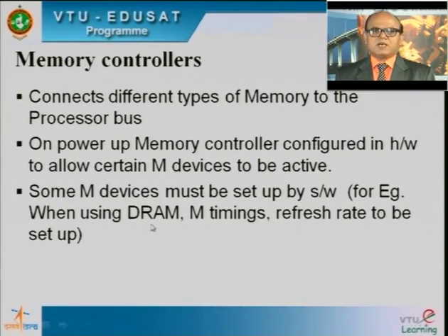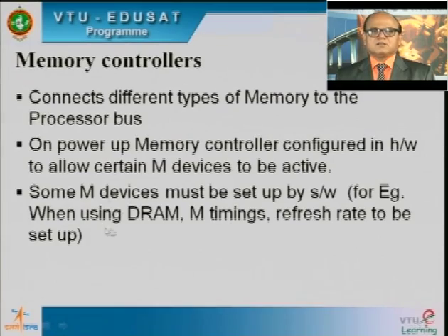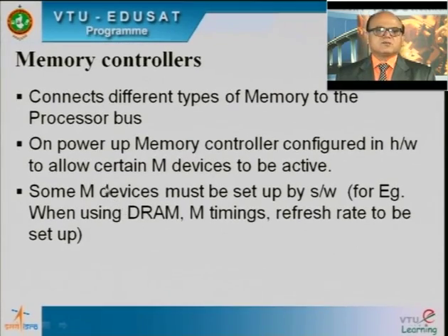For example, when using DRAM, memory timing is to be decided after every power up. Similarly, the refresh rate is to be set up. So every time at power up, the memory controller does this kind of operation.